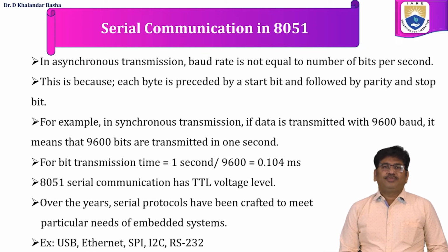In asynchronous transmission, baud rate is not equal to the number of bits per second. This is because each byte is preceded by a start bit and followed by an optional parity bit and stop bits.